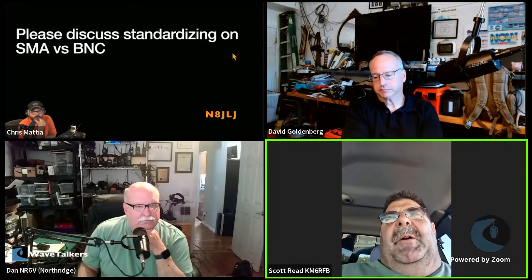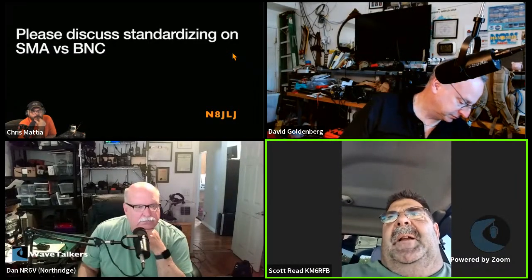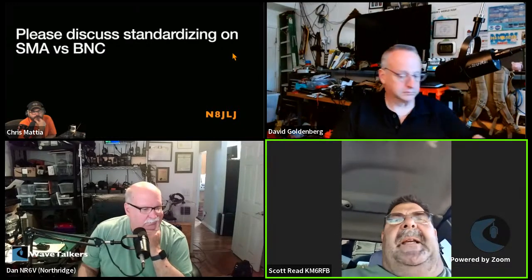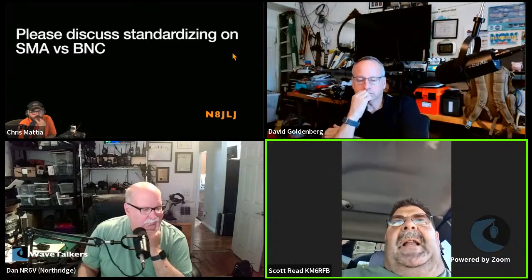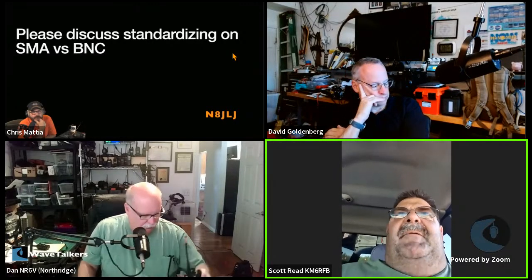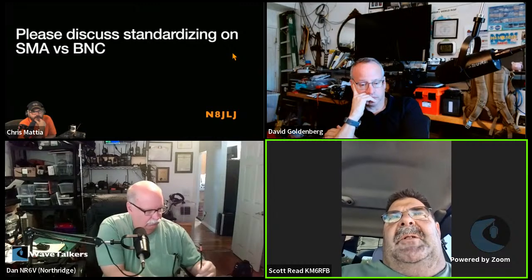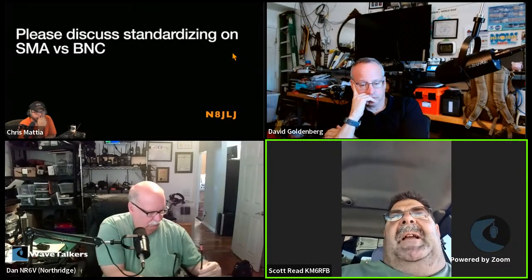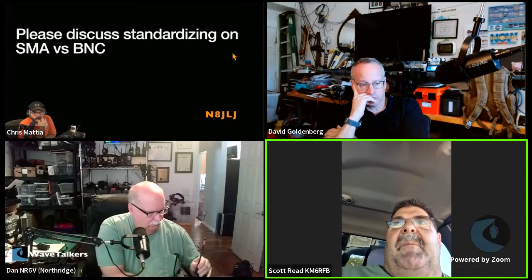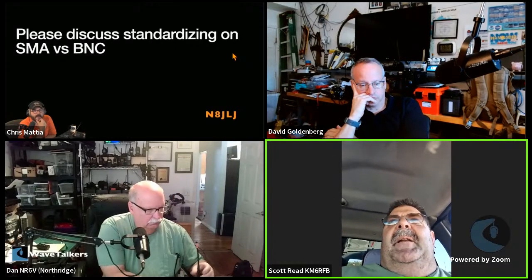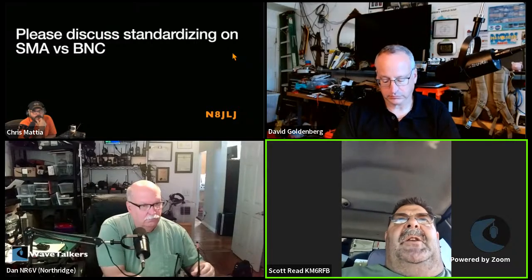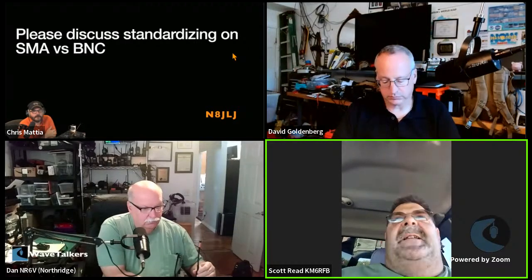Absolutely. And just to pair it with what Chris and Dan and everybody else has said, and Dave, I've gone to the point where I am now changing out all my connectors to BNC, because it just makes it a little bit more robust. And David said it quite well. Those SMA connectors have a certain limited number of turns on them before they'll lace themselves out, so just keep that in mind when working with antennas. It also standardizes what you have to carry out in the field as far as adapters and things like that.